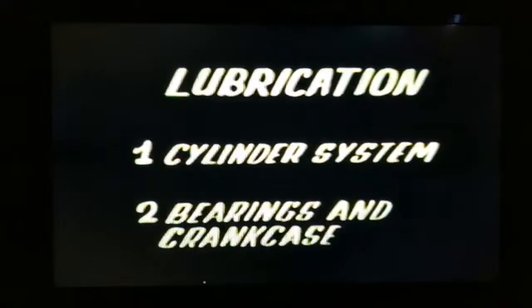Our final topic for study of air compressors is lubrication. Lubrication of a compressor is the most important part in its care and operation. Lack of proper lubrication will damage many parts. Reciprocating compressors have 2 separate lubrication systems. One supplies oil for the cylinder, the other for the bearings and crankcase.